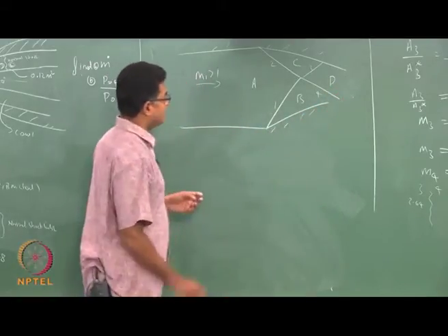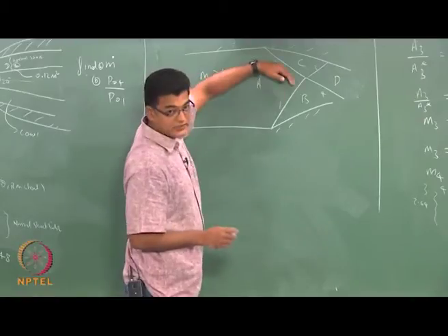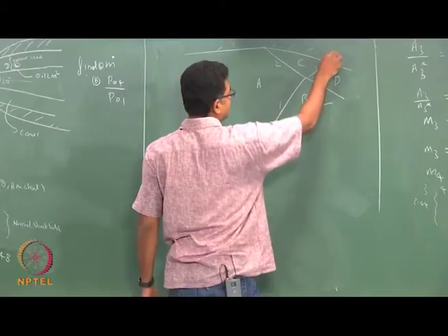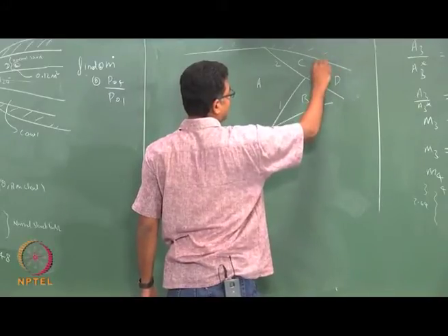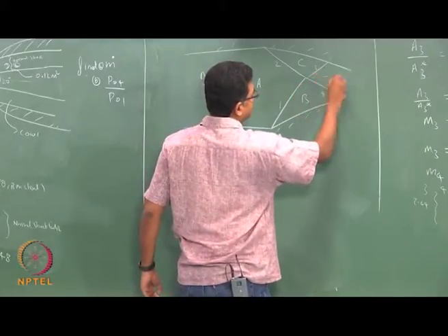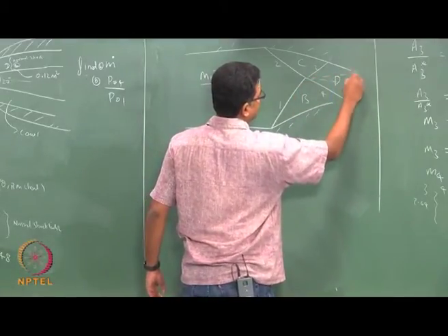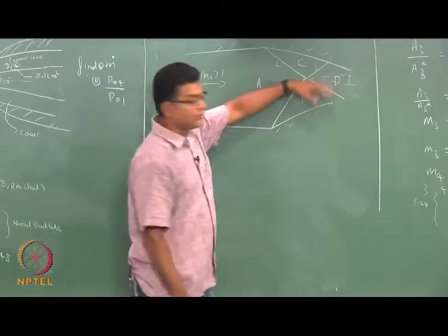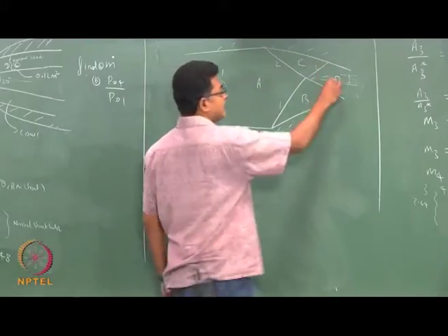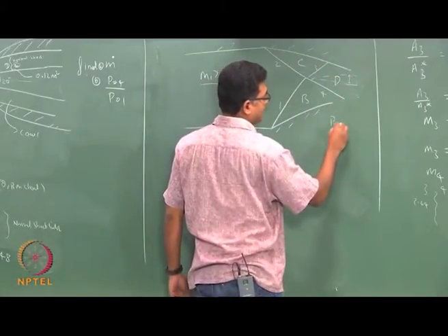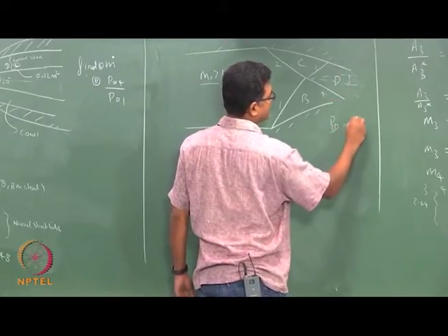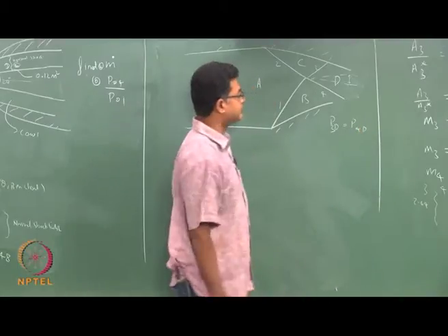Okay. So, the first reflection is very straightforward, you can do. Then the second reflection also you can do, and some of the things are true, but then here you will have two slip lines. So, you have to do it iteratively to get this particular region where the pressure in D, say for example 3D, and pressure along 4D are the same.